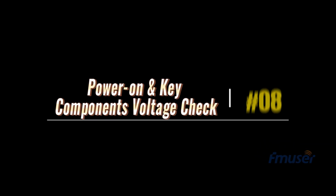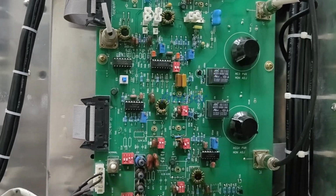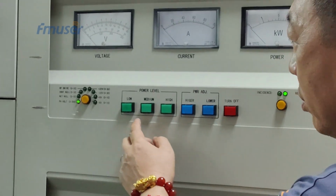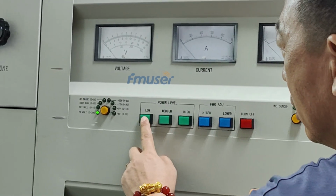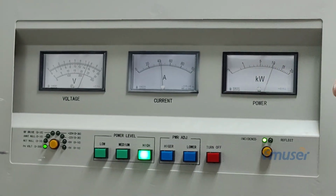Step number 8. Power on and voltage check for key components. Ensure that all components are in the correct position before turning on the transmitter. Focus on the power level section in the tuning control panel. This 10 kW AM transmitter has 3 default output power modes, allowing engineers to fine-tune the power using higher and lower options. The available power modes are low, medium, and high, corresponding to power levels of 1 kW, 5 kW, and 10 kW respectively.